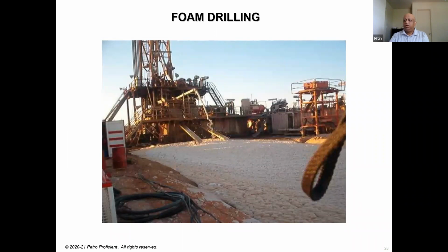Basically this is how it looks on the rig side when you have a foam being drilled. If you can see here, you have your blue line here that will basically eject all the foam into your waste pit. And this is how the foam is collected on the rig. This foam can be either recycled or it is wasted, but it is environmentally friendly. So with time, this foam will disintegrate. It is just surfactant and water basically.